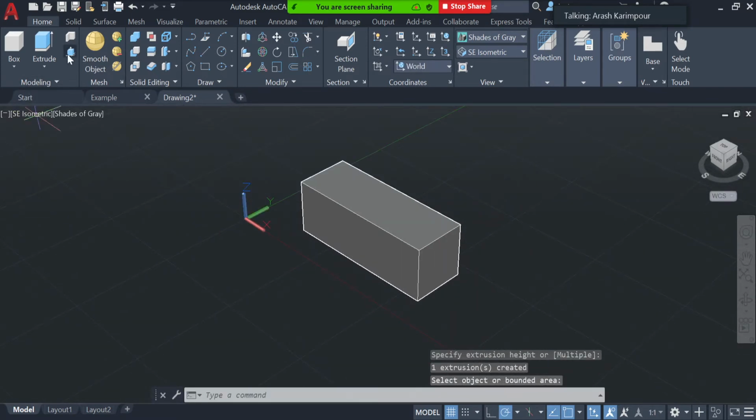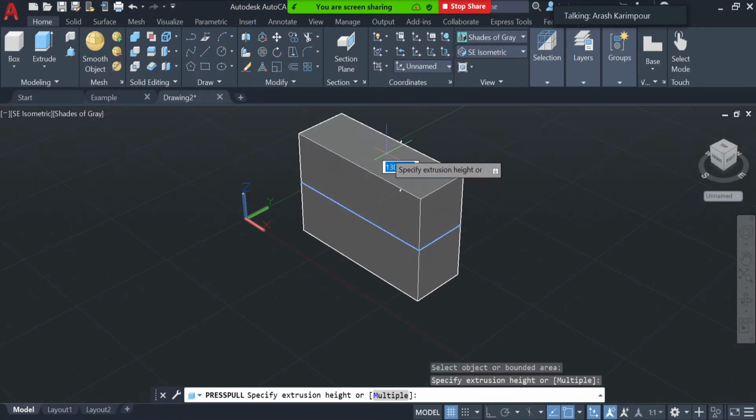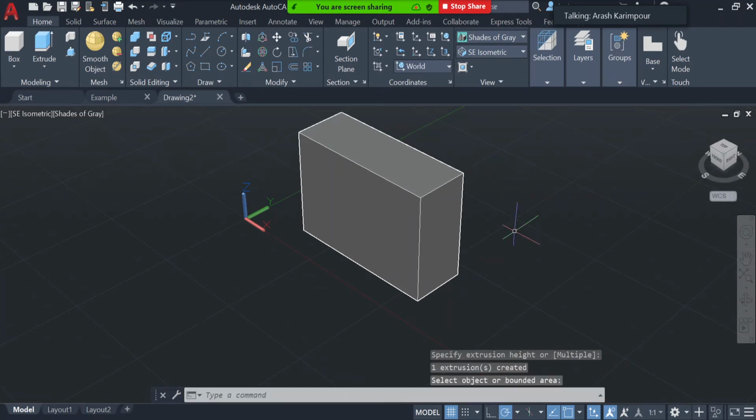Again, I can come here, select the Presspull, and, for example, select this top surface and Presspull it up to here. So even after you do the Presspull, you can still use the Presspull command to press pull from any newly created surface.